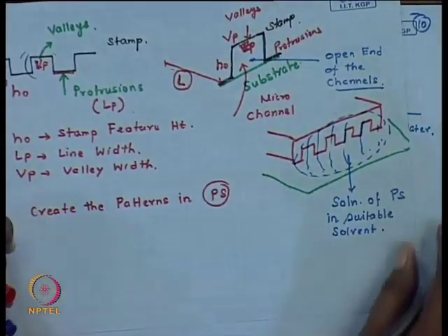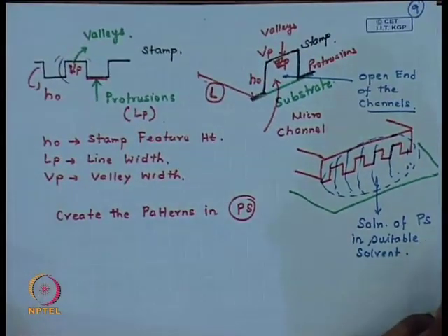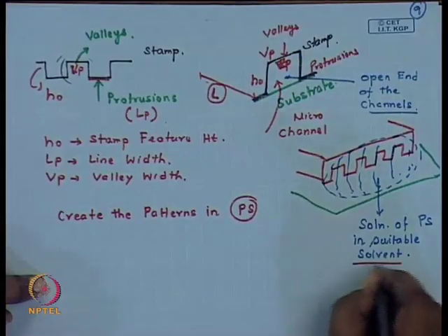we know that. So, similarly here when you dispense the solution, the polymer solution, you are not using water. So, hydrophobicity or hydrophilicity really does not matter, but what matters is whether the stamp wall, the material of which the cross-linked polydimethyl siloxane which you are using here for making the stamp, whether the stamp wall is preferentially wetted by the solvent, mainly the solvent of this solution.